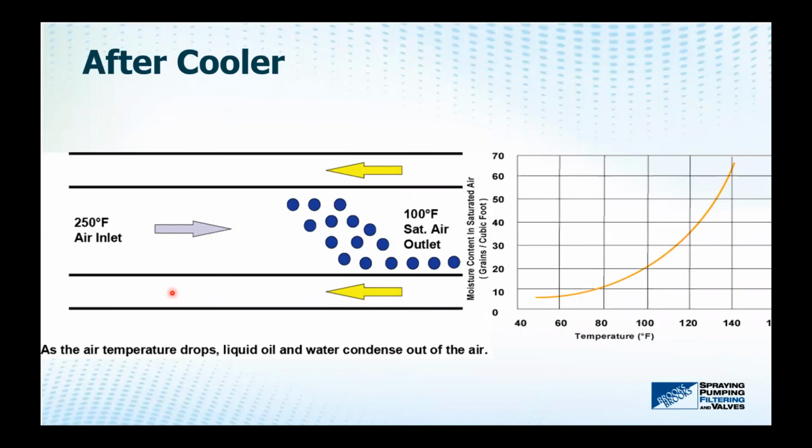On the other hand, if you had an air-cooled aftercooler, it probably has a 25 degree temperature approach. So if you came in at 250 degrees F with a 25 degree approach on an 80 degree day, your outlet air would be 105 degrees F. So, as Zenon mentioned before, we want to get this air temperature down, not only for safety reasons, but also to condense as much of the vapor as we possibly can, because it's easier to take out liquid. Yeah, good point.